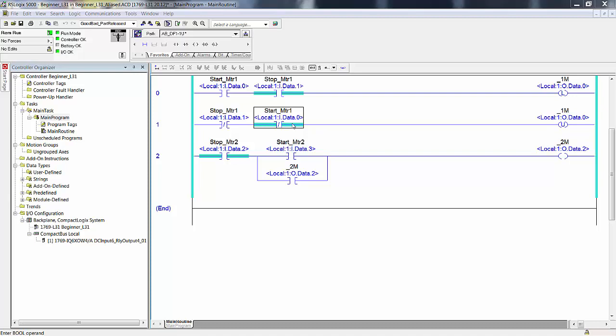I mean, I instantly look at this and see that that's not off because it's not true. This is a true if off instruction. It's not true, therefore it's not off. It's on, as you can see up here. If a true if on instruction is highlighted, then that bit is on. If the true if off instruction is highlighted, then that bit is off.